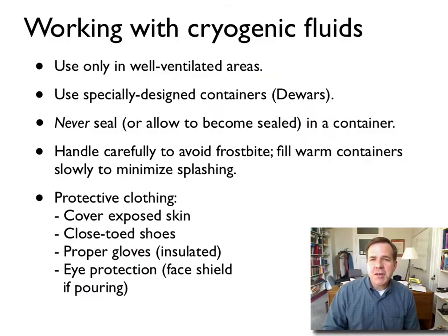So with that as a cautionary tale, how do we work safely with cryogenic fluids? Well, the first thing is to use only in well-ventilated areas. This is to reduce the danger associated with asphyxiation. We should only use cryogenic fluids in specially designed containers known as Dewars.